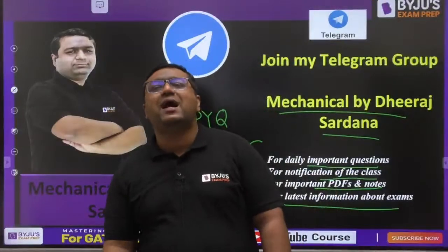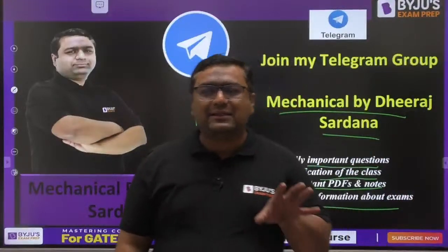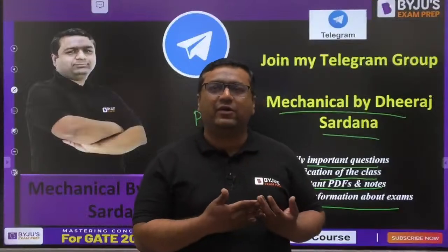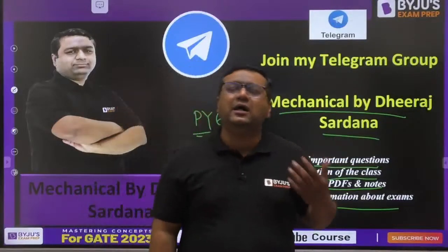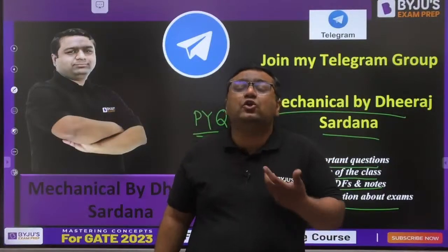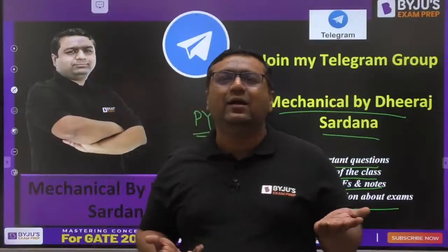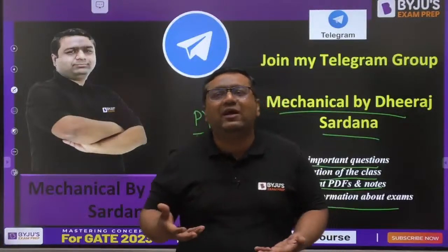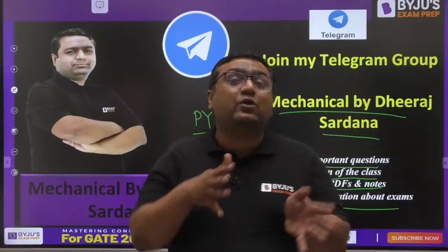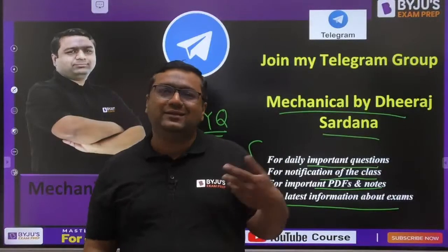Dear, Young's modulus of elasticity is a constant, and elasticity is a property. Elasticity is defined as the property by virtue of which a material regains its shape and size. Whereas Young's modulus of elasticity defines how much load you need to apply to give a deformation of the material. So both are properties, but Young's modulus is explained in a mathematical term. You are defining the stress value per unit strain, that is said to be Young's modulus, and that is also defined only up to the elastic limit. So guys, when we are talking about the properties, this is how we can differentiate.